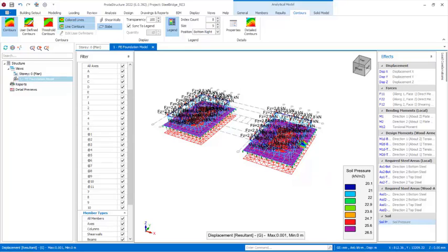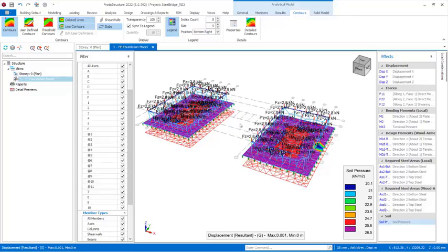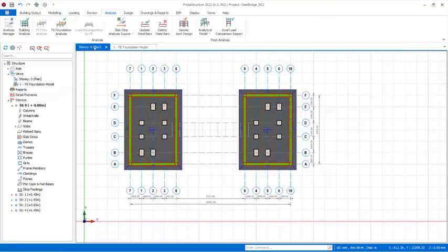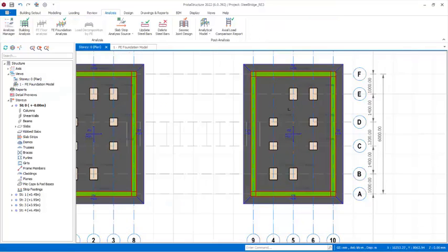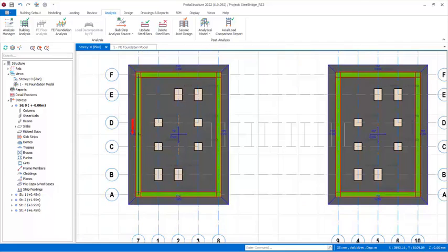So what we have to do is navigate back to the physical model, since we are done with the analytical effect of the finite element method successfully. So we get back to the physical model, click right there. So this gets us here. The next thing we will do is to generate reinforcement for the foundations.